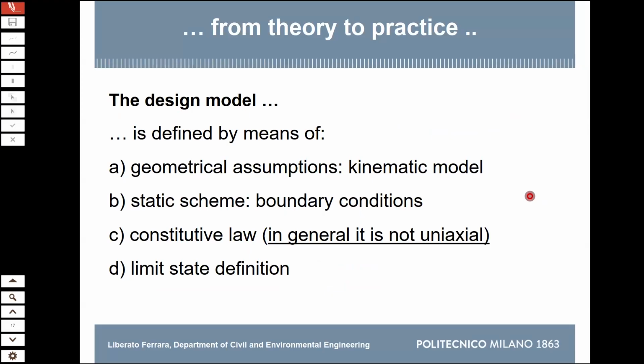That is a model that luckily those kinds of elements obey very well up to failure. But that is a model. It implies that the cross-section remains planar, and from that assumption, everything comes in a very clear and elegant mathematical formulation that we can easily handle.